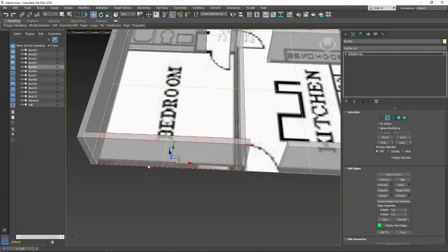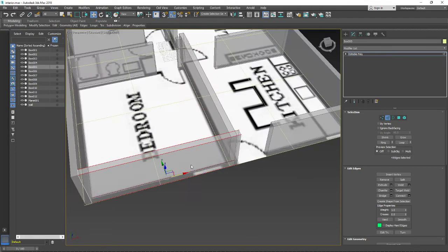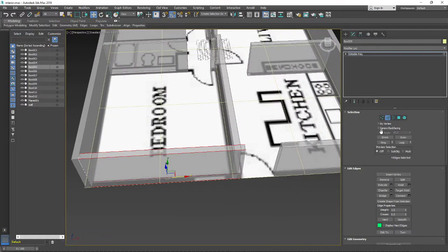If you have some problems on your mesh, the ring selection will not work correctly. So when you select all the edges here, you can just use the connect button over here, and now let's put these edges where the window actually ends, over here. And the same thing with that other part of the window.